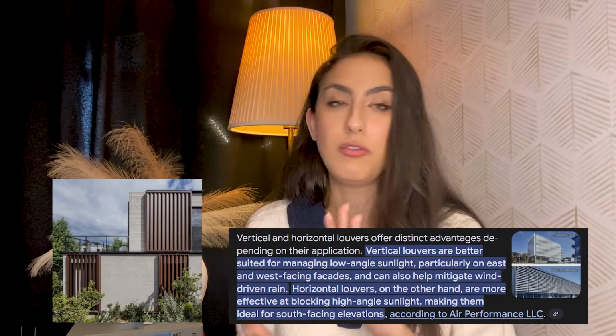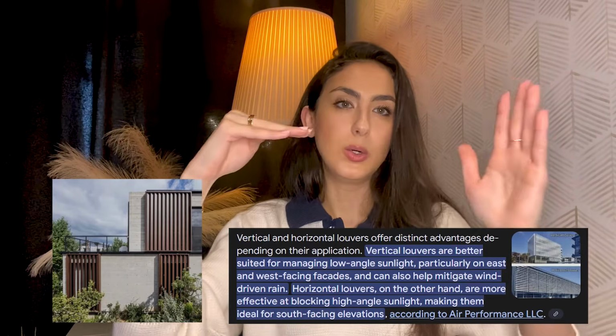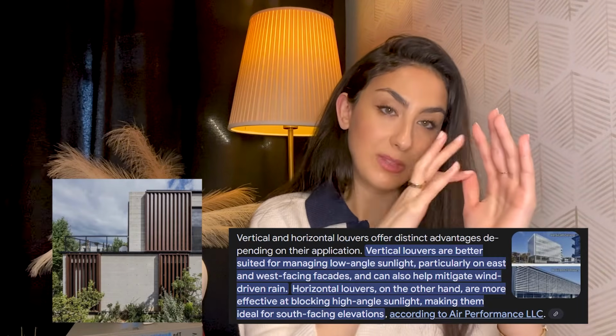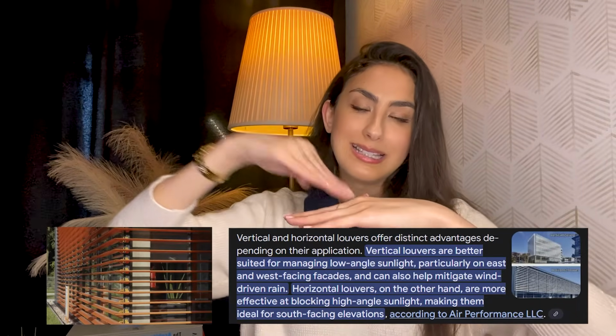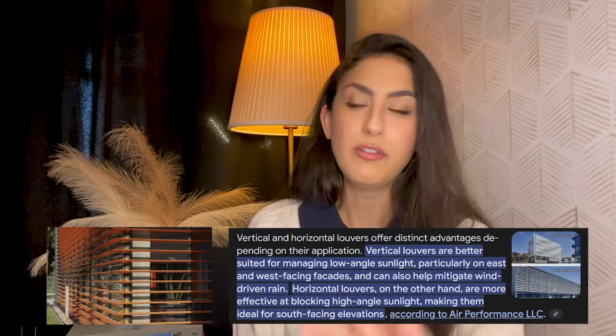I think I do want to mention one more thing about that, is when you have a facade that's facing west, you do want to use vertical slats, because the sun is very low, and then it's not gonna go through the glass or whatever opening you have. If you have a south facing facade, you're gonna get a lot of afternoon noon sun, which is really high, so you do want to have a lot of horizontal so the sun is not going to be able to go through. So just a quick tip based on what facade you are facing.